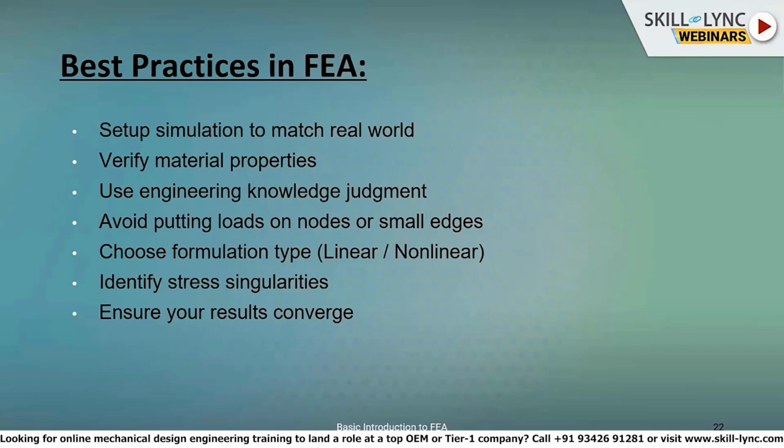Then identify the stress singularities. Ensure your results converge properly. 100% your results are going to converge, that you have to understand. So these are the best practices which you generally follow while you are doing the FEA.